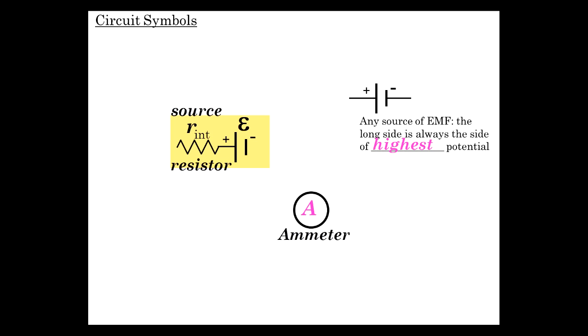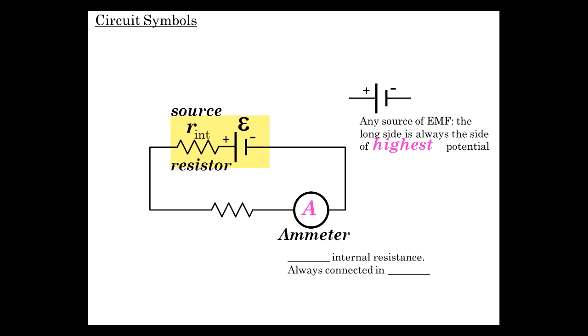And it has to look like essentially a zero resistance element. Otherwise, it's going to affect the circuit. Okay, so we're going to hook it up in series through another resistor here. And there we have a little circuit, complete path. So low internal resistance on the ammeter, always in series.